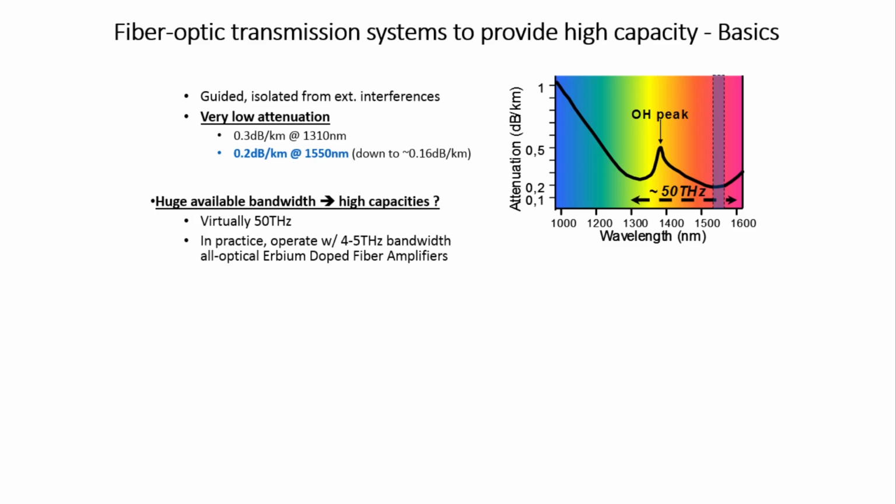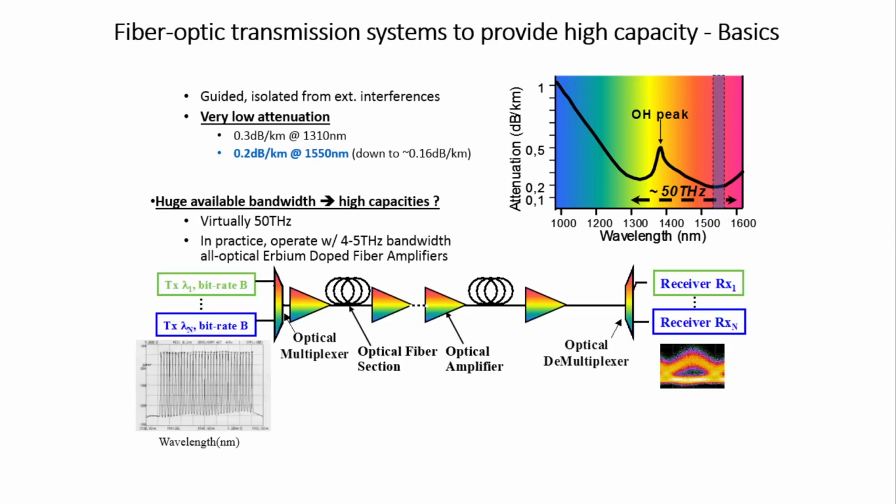Huge available bandwidth, high capacities, virtually 50 terahertz. In practice it operates over about 4.5 terahertz bandwidth, with all-optical erbium-doped fiber amplifiers.